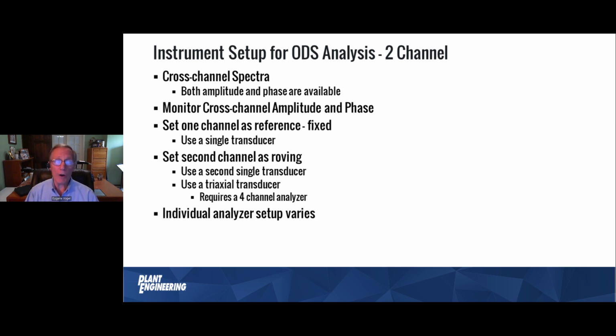And it can compare that vibration signal from the second transducer to the vibration signal from the first transducer, just as a single channel instrument was comparing the vibration to the reference pulse. It simply compares it, the two-channel analyzer, to your reference vibration pickup. Okay? So it works really good.